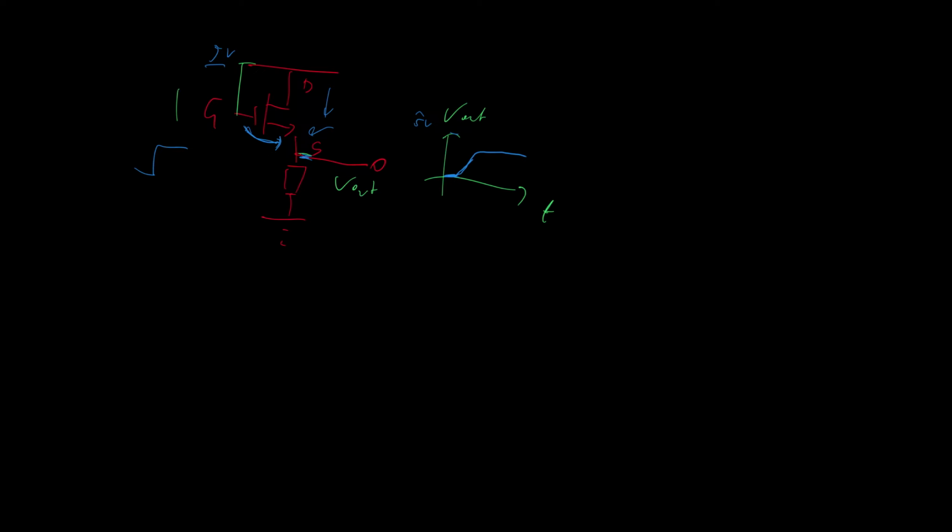because to keep the FET open, we need the gate to the source to be a large voltage. As the voltage increases here, it's turning off the FET. So we're going to get to some equilibrium where the FET is neither fully on nor fully off. So this design is not going to work.